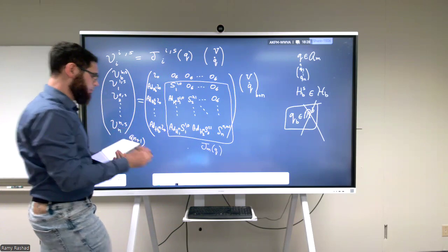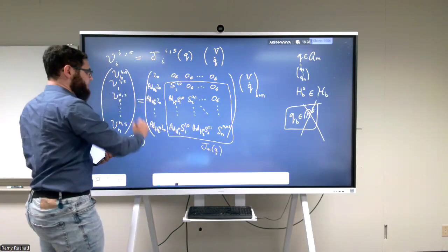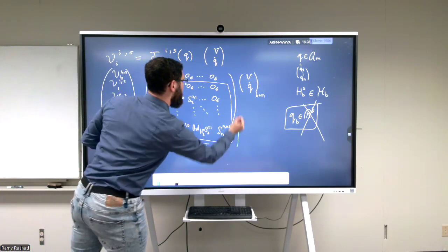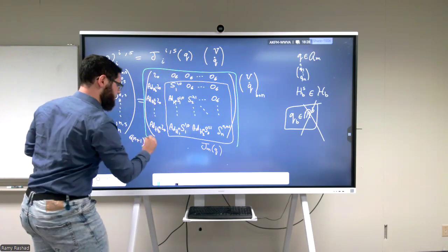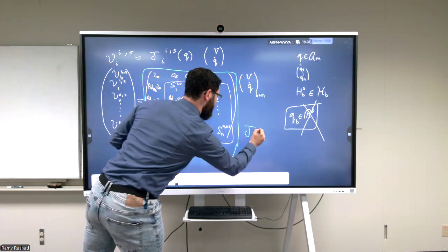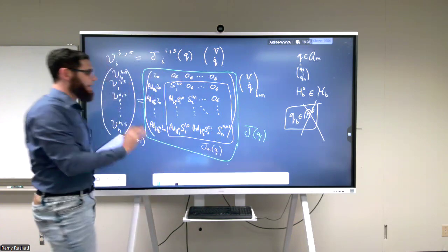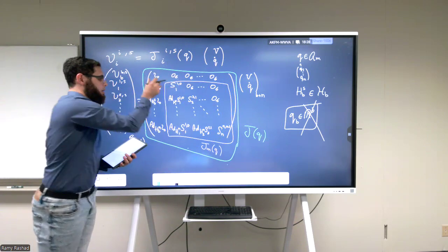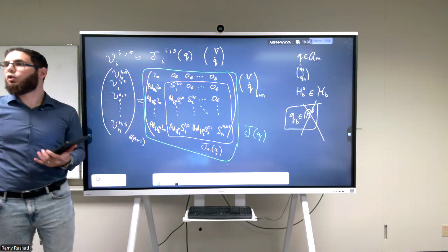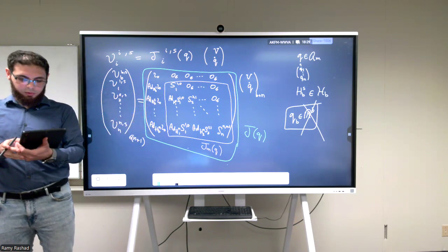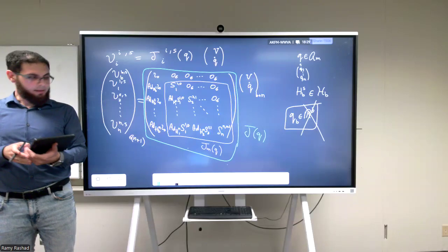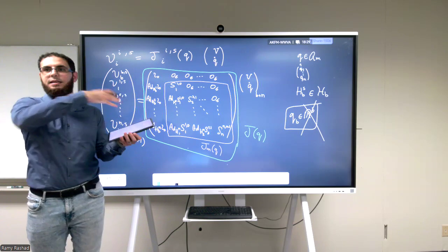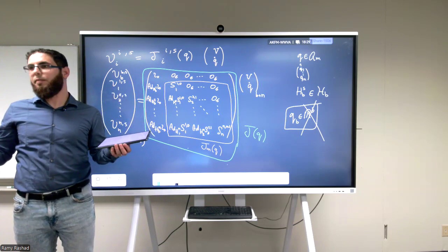So this whole thing is the Jacobian as a function of Q. It has a base part, it has a manipulator part, this is zeros, and this is the coupling that will cause the base and the manipulator to be related to each other. And again, there is more that we can go into, but this is the key thing. If you really understand this, the rest is just a bit of math.